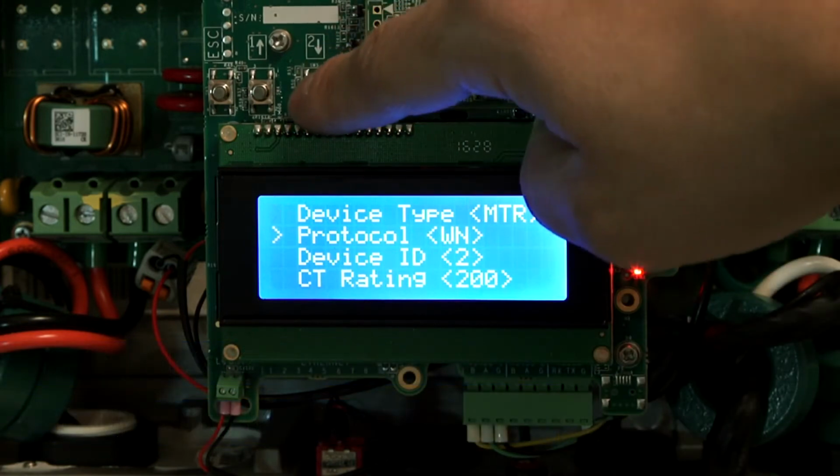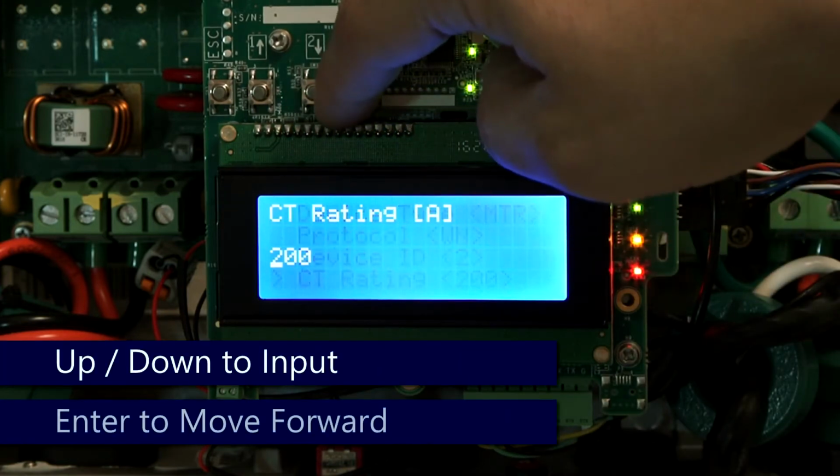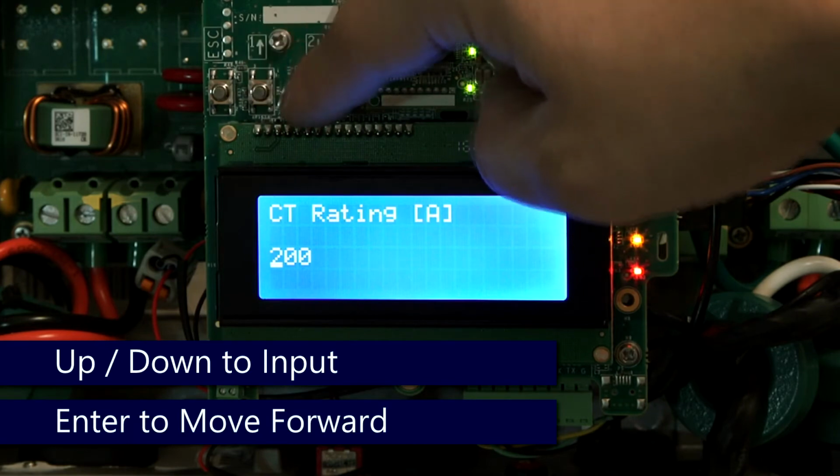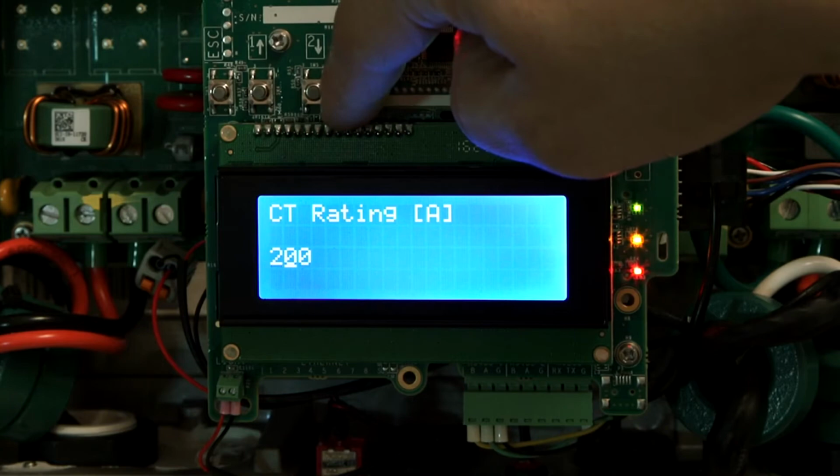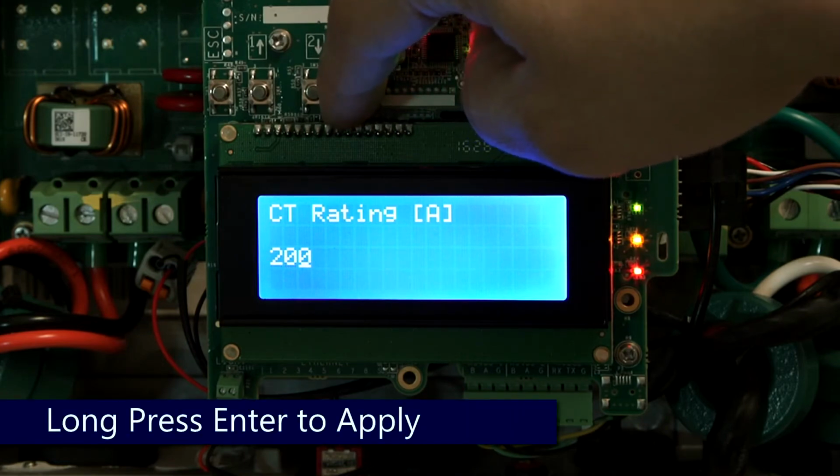If you need to enter your CT rating, select and use the up and down arrows to enter in your value. Enter to move forward, escape to move back. Once your value is entered, long press on enter to apply.